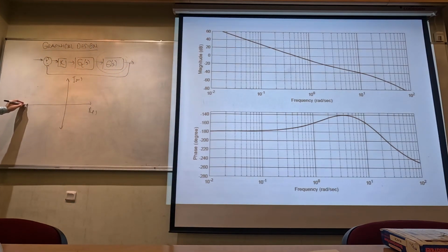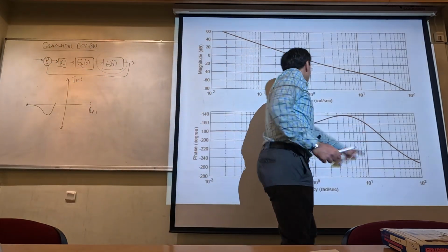So this Nyquist plot is going to start from here. Infinite magnitude, minus 180 angle. Then the angle goes to minus 160, etc. So this thing is going to come somewhere here, so that the angle comes to minus 140. Okay. When the angle comes to minus 140, it is going to go in the reverse direction, and we are actually going to cross the minus 180 degrees.